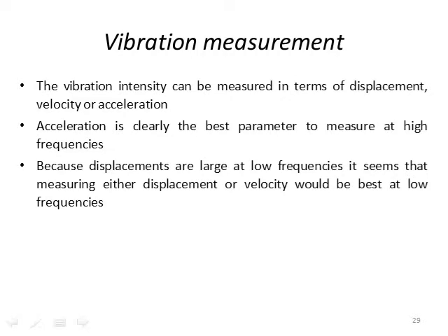Now in a vibration measurement, the vibration intensity can be measured in terms of displacement, velocity, and acceleration. Acceleration, quite importantly, is clearly the best parameter to measure at high frequencies. And for low frequencies, low frequency displacements are the best way to measure.